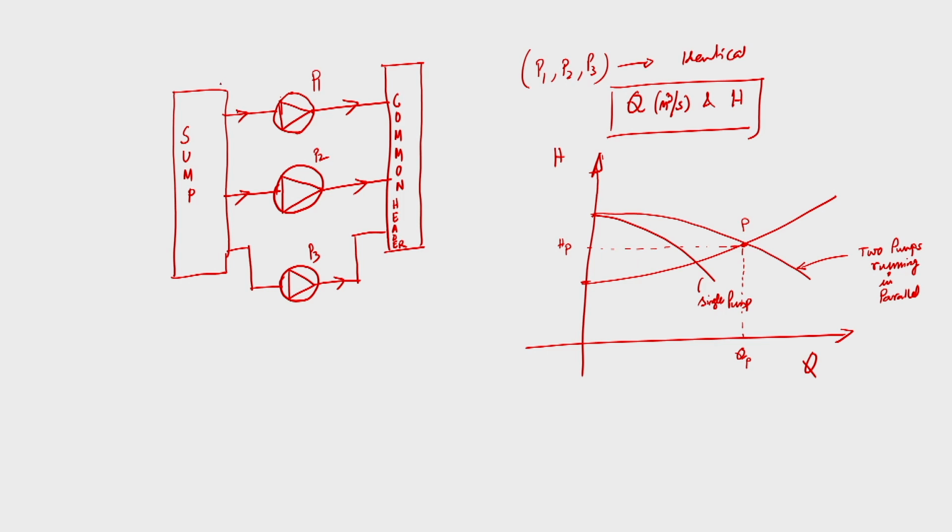Now, as I said long back, whenever installing another pump, it is not possible that we will get the same pump from the pump manufacturer. So, anyway we have to have another radial flow pump, and the pump will be of the same speed. If we install another new pump in parallel with the existing pumps, and both are now connected in parallel, suppose this is the newly installed pump, and this is now connected to the common header.